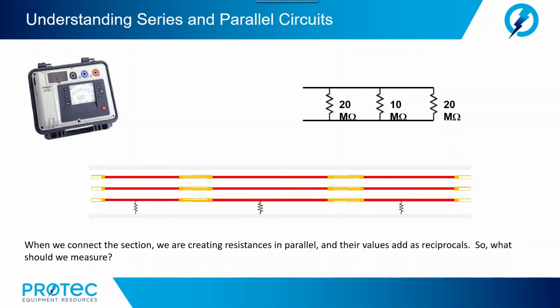Now we go ahead and we join the bus sections together to form the full busway, and now, in final inspection of the completed assembly, we measure the insulation resistance phase to ground once again. What do you believe the final resistance value will come out to be?